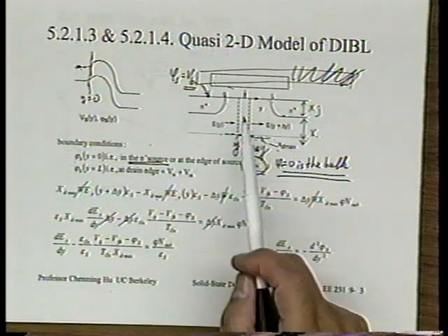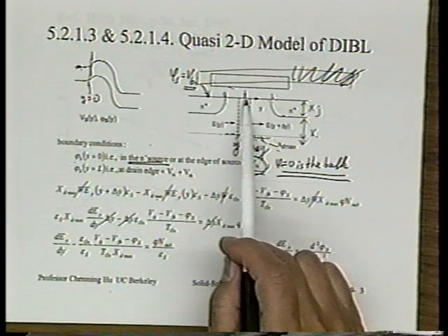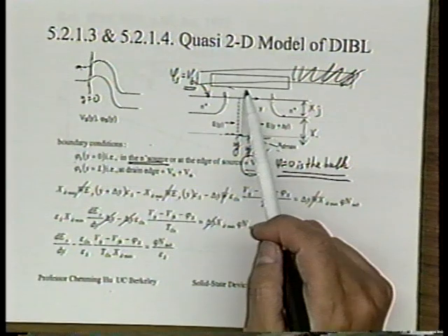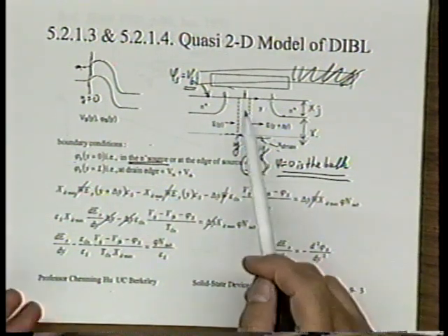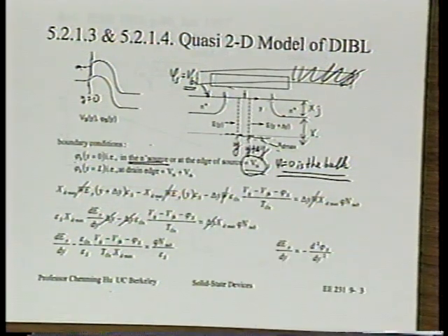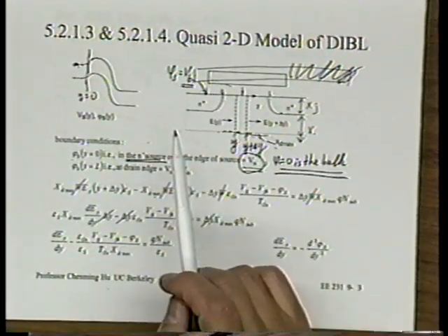The third boundary is the interface. How would you figure out the electric field at the surface of this box? That is related to Vox, the voltage related to the electric field in the oxide. Isn't that right? If you know the electric field in the oxide, multiplied by the ratio of 3, or divided by 3, you get the electric field in the silicon surface, right? And what determines the electric field in the oxide? It's just Vox divided by Tox. Is that right?